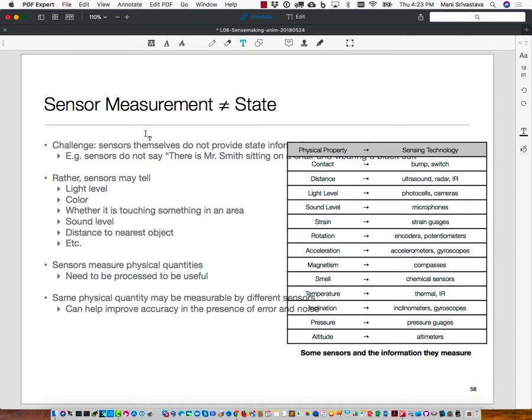Okay, and again, topographic information about the world is pretty readily available, certainly for the US. There's a government website where you can go and get this information. And now again, it becomes a sort of matching problem. That is, I have to take this altitude plot that I got from the barometer and find out where it would best map to on that topographic map that we have. So I can infer location.